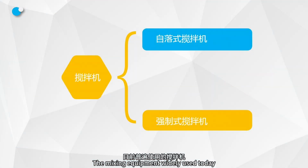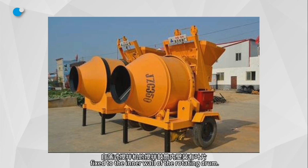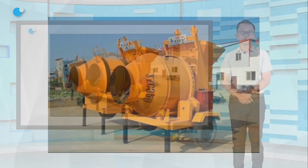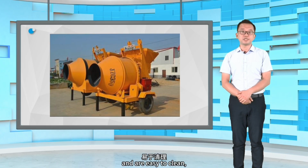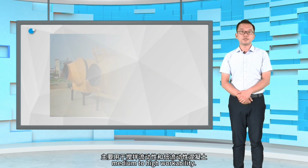The mixing equipment widely used today can be categorized based on mixing mechanism into drum-type and forced-action mixers. Drum-type mixers have blades fixed to the inner wall of the rotating drum. As the drum rotates, the blades lift the concrete mixture upward and let it fall under gravity, achieving a uniform mixing. Drum-type mixers experience less wear on the drum and blades, and are easy to clean, but their mixing power is relatively weak. Energy consumption is higher, and efficiency is lower. They are mainly used for concrete with medium to high workability.